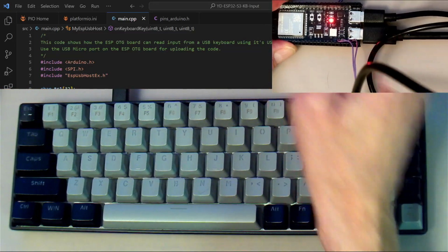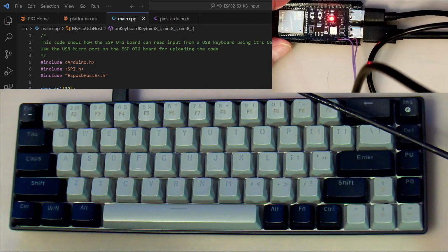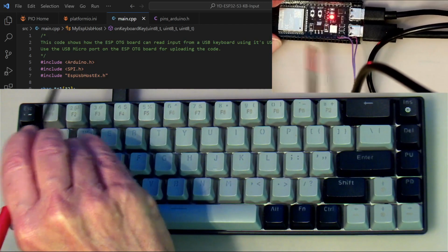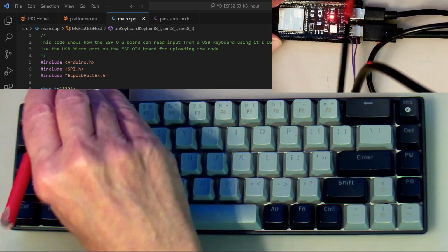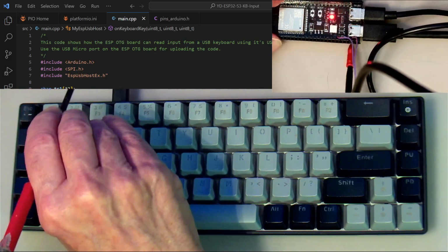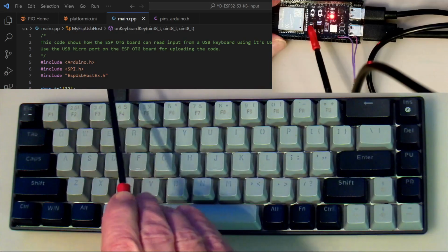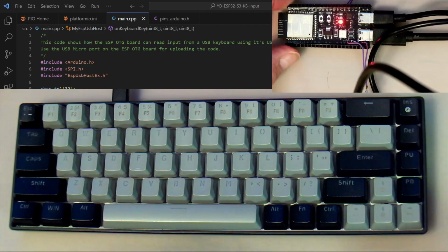There's another pad there that says external power. So I would be able to plug in this little header over here, plug some 5 volts into the port over here and power it from there. But this one does not have any battery charging circuit. But in any case,